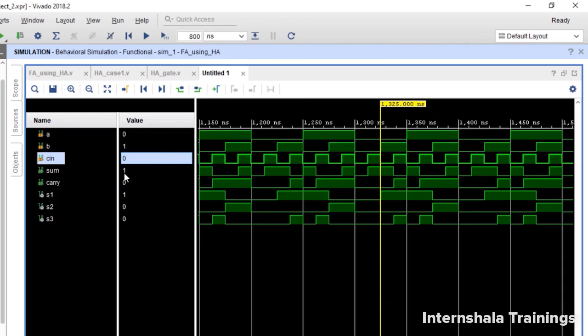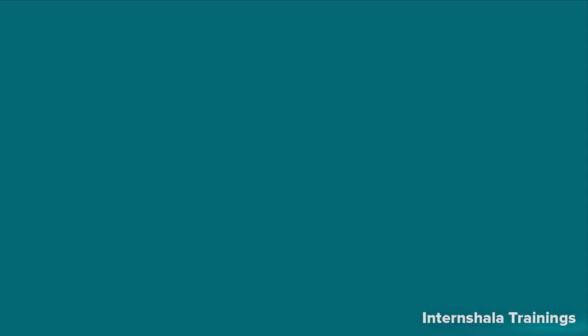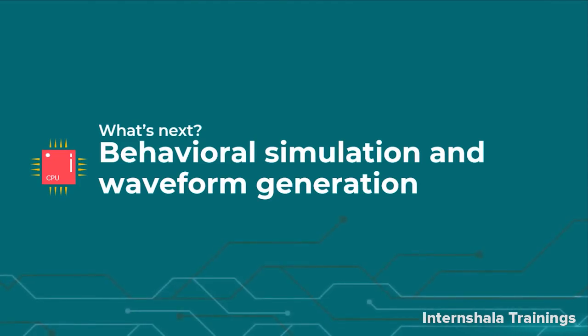0 1 0 sum is 1, carry is 0. Let us check one more. 1 0 0 sum is 1, carry is 0. And here 1 0 1 sum is 0, carry is 1, and 1 1 1 sum and carry both are 1. So everything is working fine in the simulation as well. So students, now we have designed as well as implemented a full adder using module instantiation.